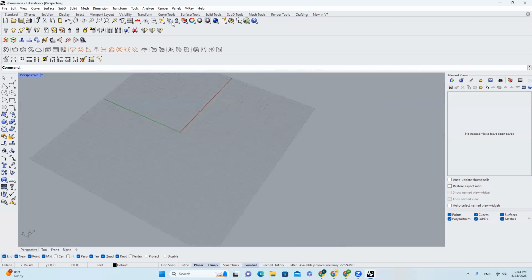And the next thing I want you to know is this visibility. So for example, if I created multiple points right here and I want to select this and hide it, all I have to do is select those 4 points and click hide, right? But if I want to hide everything but those 4 points, what I will do is come over here to this triangle and then click isolate objects. Okay, so you see you hide everything else except the objects you just selected. So this tool is very handy. I will Control Z, which brings me back to the previous step.